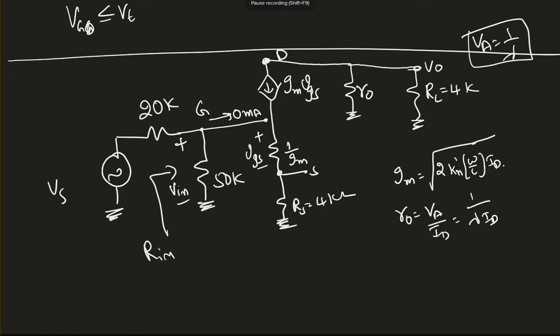So there are a few parameters. That's gm, the transconductance, that's the formula you need to remember, and R0 equals VA over ID. ID we found in DC analysis. Sometimes instead of VA they will give you 1 over lambda. In this example he gave us VA equal to 100 volts. That's given by the manufacturer.